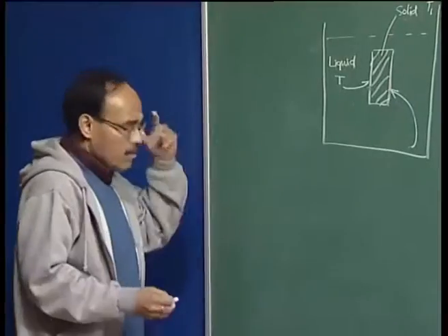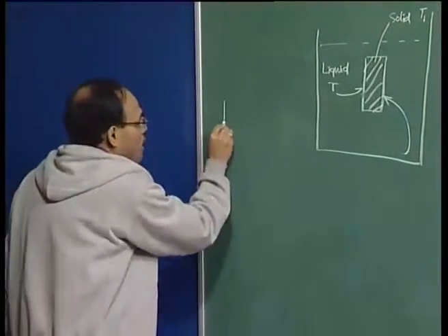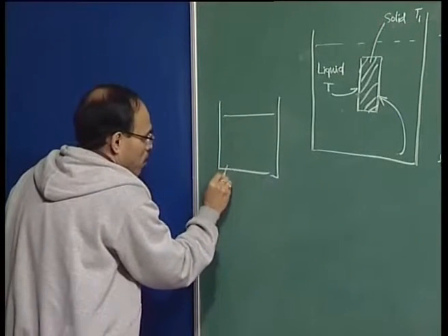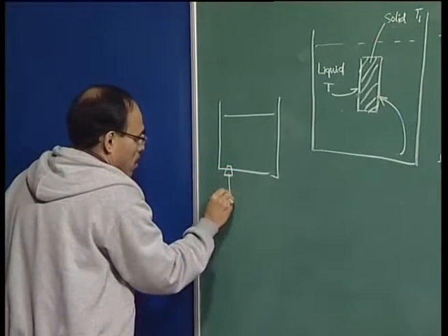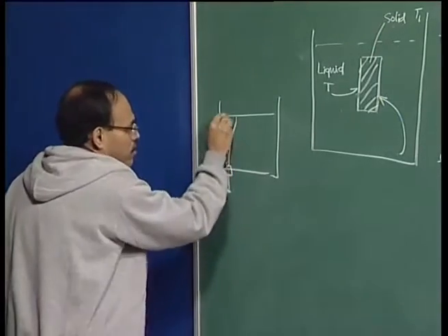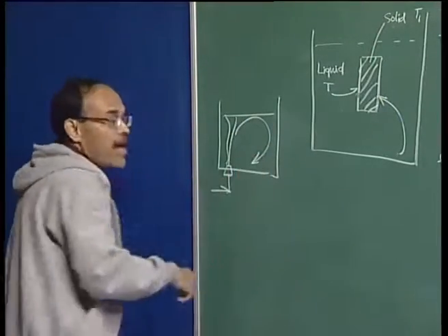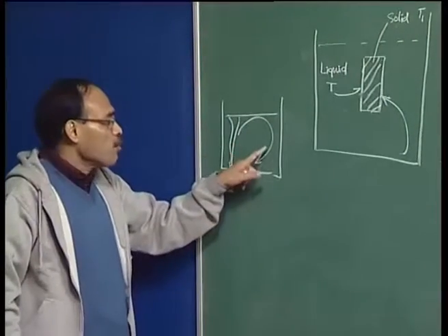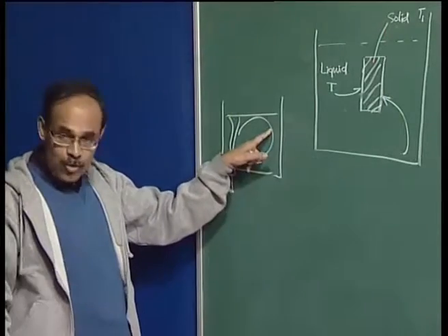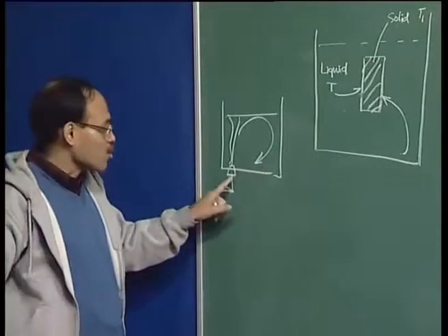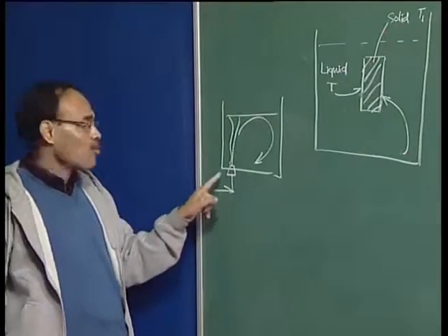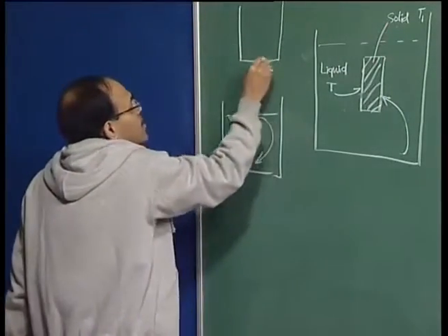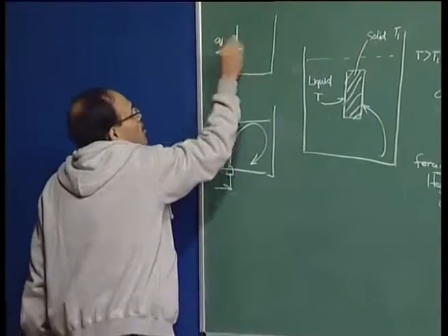So, therefore, in the context of steel making, I would say if I have a ladle which contains liquid steel, and I have a porous plug here, and I stir the contents of the ladle, and there is a motion, this motion is going to aid the distribution of heat in the system. So, heat will flow from one point to another due to convection, of course, and that convection is going to be forced convection, the origin of which here is gas injection. On the other hand, I can have a ladle with no gas injection, but heat is going to be lost from all surfaces.